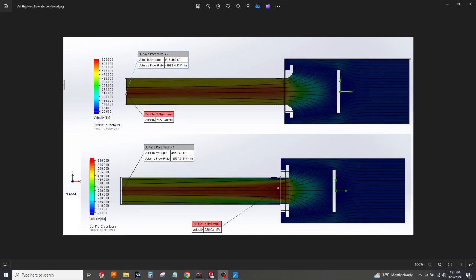And in fact, that's because of the whirly bits. We really are essentially stagnant. And then if you look at the velocities as it goes down the tube, there's a much more significant gradient from the sidewall to the center of the tube. And that's never a good thing. What we really want to strive for here is having the closest thing to the same velocity throughout the entire tube as possible.